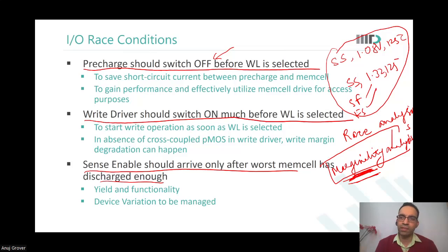That's okay? You wanted to apply brakes and it accelerated the car. Fine with you? You will sit in that car? No sir. So it's a failure. Yes sir. Now for the NAND gate, you could probably slow the clock and say, instead of latching the NAND gate after 20 picoseconds, I will latch it after 30 picoseconds, and you could recover yield. Yes sir. In the memory, you can't do that. In the memory, the sense amplifier enable is not controlled by you. It is controlled by the memory itself. You slow down the clock as much as you like, the enable will still come at the same time. So this is a permanent yield loss.